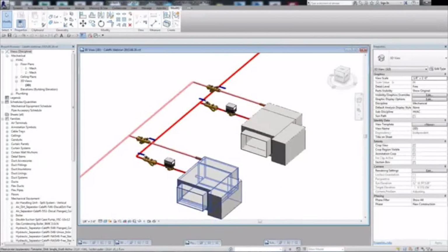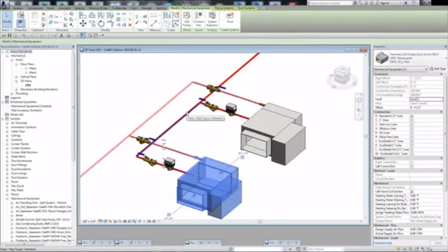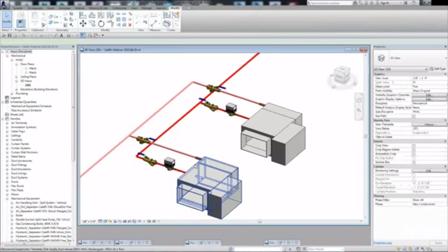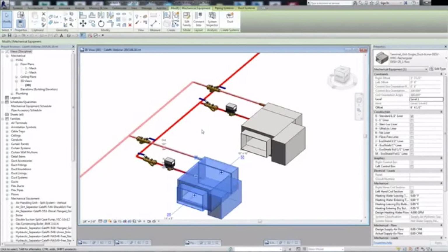So within the VAV boxes, for an airside system, a VAV box is going to be kind of a middle component, meaning it's calculating from the diffusers, taking through the supply air, and pushing it upstream all the way back to the air handling unit. So for the air system, it's going to be in the middle. But for a hydronic system, it's really an end component. And what I mean by that is this component is going to determine the load on the flows for the hydronic system.